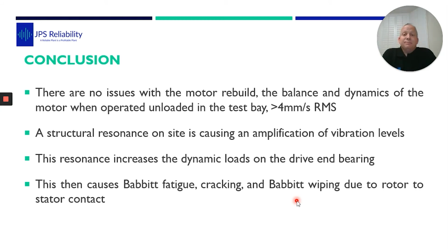Well, we concluded no issues with the motor repairers. We did an acceptance test in the workshop, put it on site. That motor is fine. But it's coincidental now that at the running speed, we're getting a structural resonance, which is amplifying the vibration, increasing the dynamic loads on the drive end bearing. This then is causing the Babbitt fatigue, cracking, and failure.